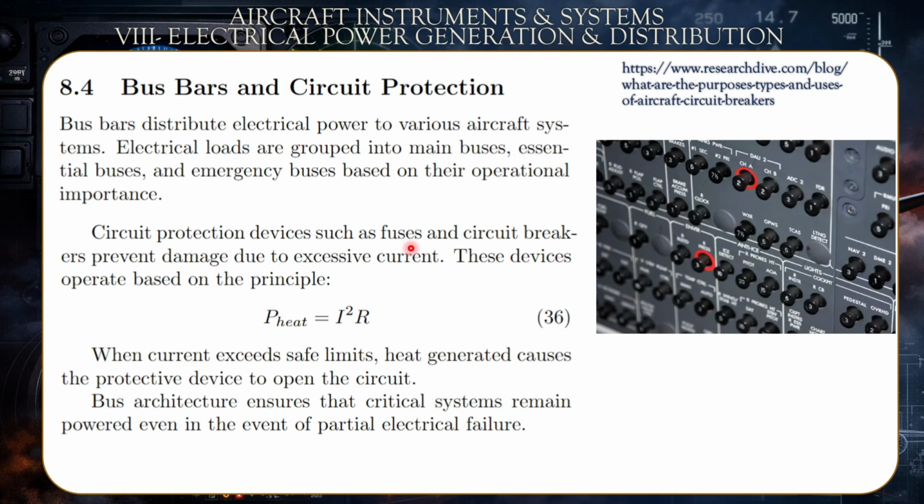Now, the fuse snaps and becomes an open circuit when a specific current value is exceeded. So when you have a fuse of 2 amperes, for example, it would snap when the current goes above that threshold, which is 2 or 2.2 amperes, depending on the tolerance. Meanwhile, the circuit breaker is like an automatic switch, or a thermosensitive switch, that once the current exceeds a specific value, it would pop here, okay?